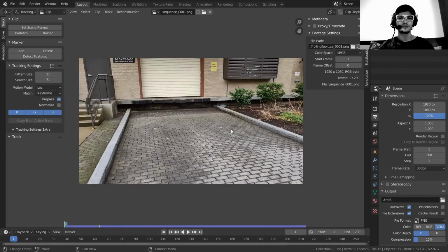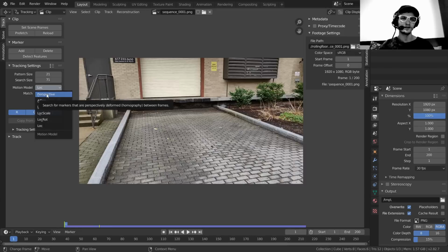Okay, so now to do our motion tracking, we need to get 8 trackers existing throughout the whole shot. At least any 8, we can switch between which 8 those are. So we're going to start off by setting up our tracker. So we want normalized so it can be invariant to lighting intensities, which I don't think is an issue here. We're also going to use either perspective or affine. Perspective is better but takes longer, but it's fine.